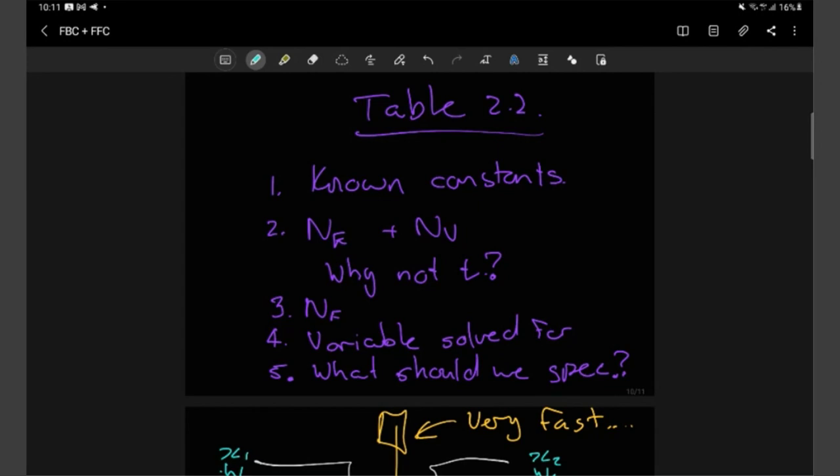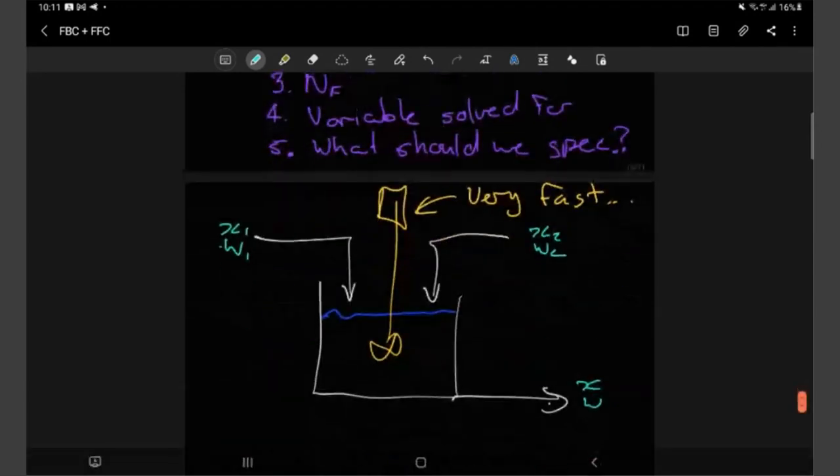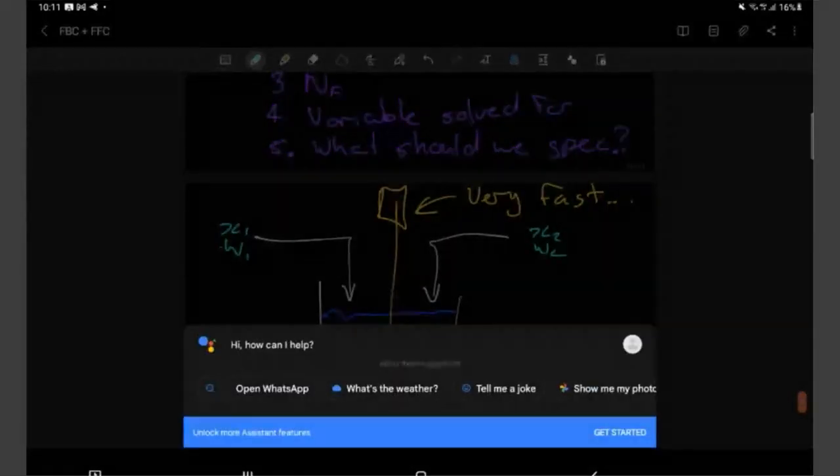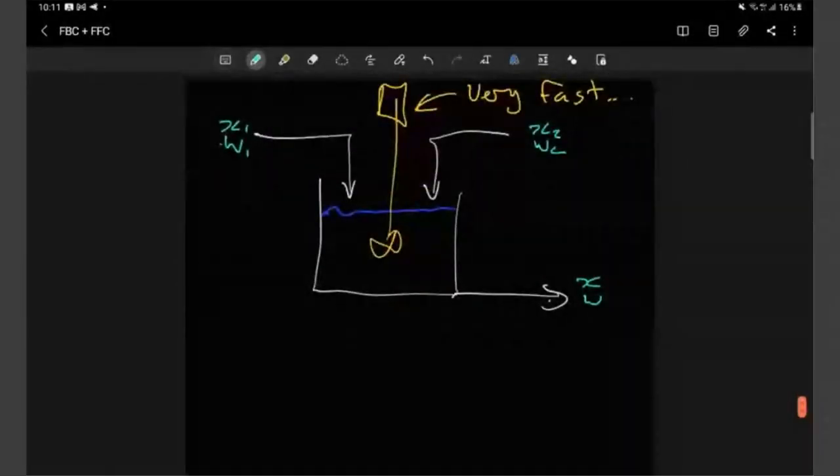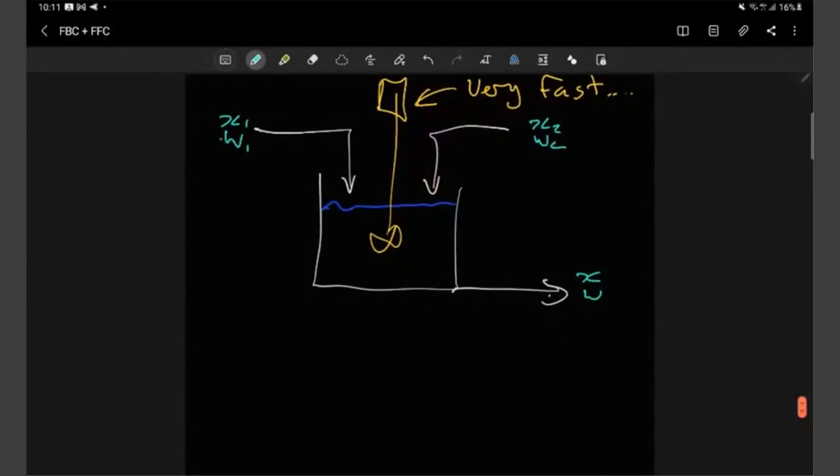So if we identify one disturbance variable, then we know that takes up 1 degree of freedom, we have 1 left. Because there's a disturbance we want to control, we need a manipulated variable, and that will take up the 2nd degree of freedom. And let's fortify this information by this extremely important example that is ever present, and you'll see that even next semester because it's everywhere.